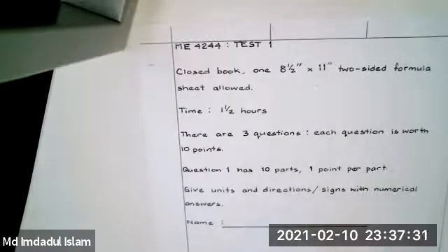Now, there is one thing that I noticed. The book has a different sign convention for bending moment. It tends to make the bending moment compressive on the bottom. The more usual sign convention is compressive on the top. Okay, I will tell you what sign convention to use in the test if there's a bending moment question.